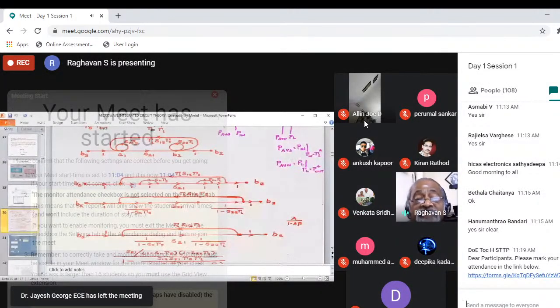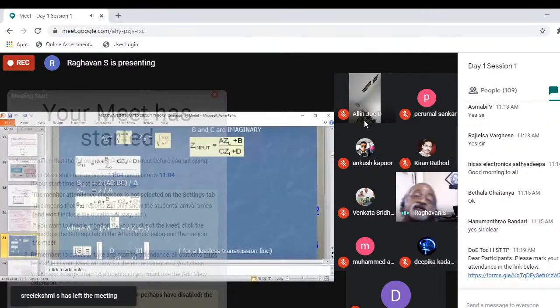If you know the conditions from each one, you can go to the other one. And this is the summary of that. And one should be thorough with the network theory. Then only you can find out the equivalent or the analogy of a transmission line to the network theory. Mainly the image impedance and iterative impedance come in the case of an asymmetrical network, whereas for a symmetrical network, image and iterative will be the same.